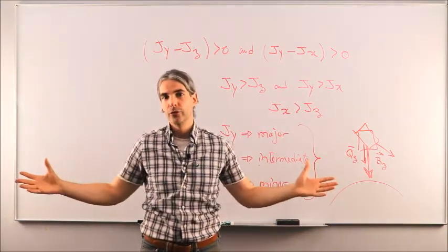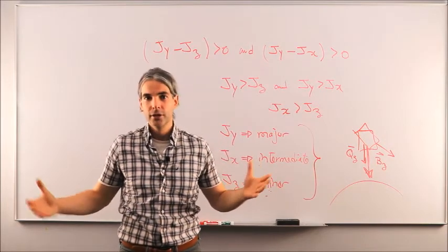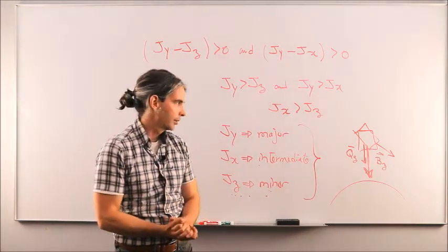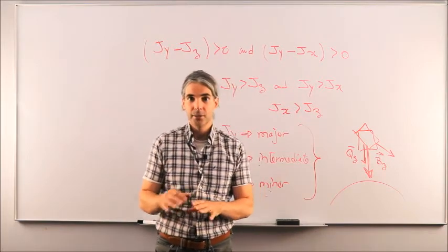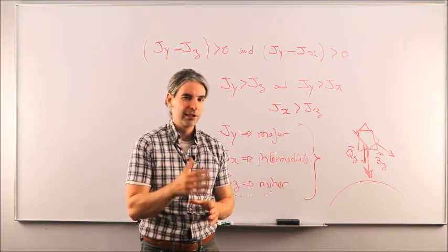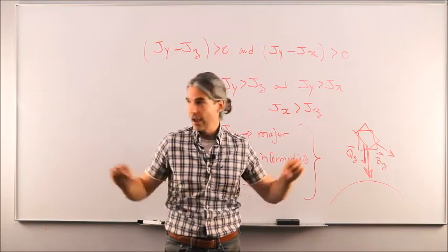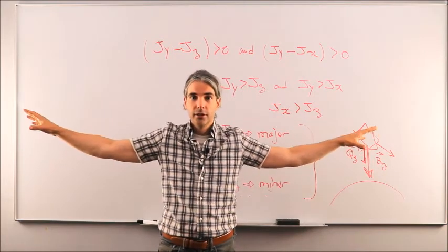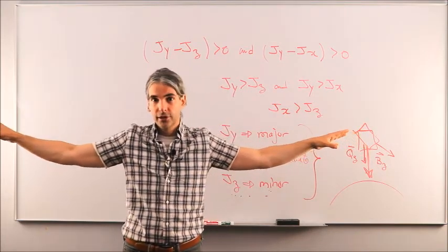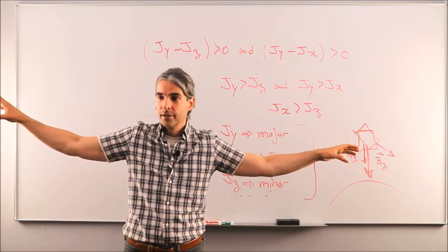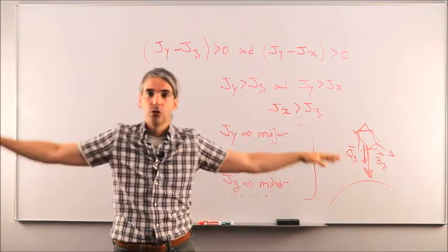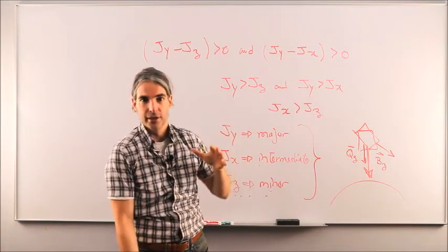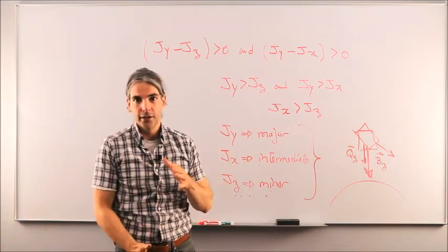Those two booms are referred to as gravity gradient booms for that specific reason, okay? And you can look up the web for gravity gradient stabilization spacecraft, and you will notice that a lot of them have those gravity gradient booms being deployed, because again, that maximizes the hold, if you will, that gravity gradient has on that spacecraft to torque it and restore its nadir pointing orientation.